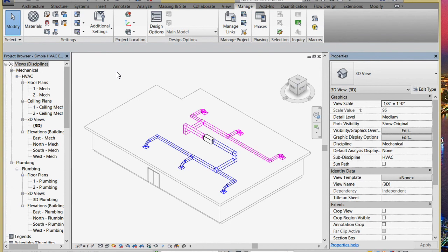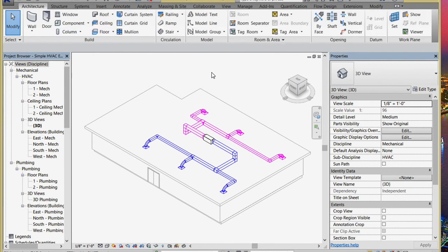Another thing we need to do just to get going with this whole exercise is if you go to the Architecture tab, we're going to use a concept which is similar to rooms. It's called spaces. And spaces, in many cases, map to rooms. Sometimes spaces don't map to rooms. It really depends on whether there's hard walls and all those boundaries. Spaces are really conditioned spaces, or spaces that are all going to share the same thermal characteristics. Okay, so that may or may not line up with room boundaries.